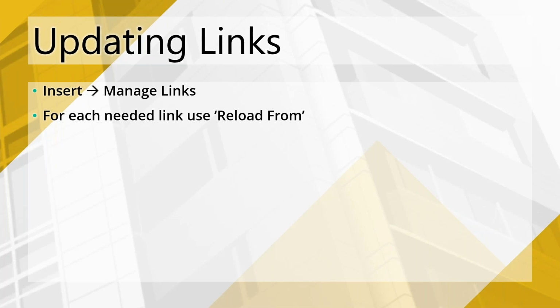Now, this is the note that I want to make sure that you understand. And I've seen people do this and it causes them pain in the future when they do get models. I recommend that you do not remove links that you don't need right now today. Chances are, at some point in the future, you may need those links. And our view templates are already set up to understand how they're supposed to work. But if you remove them, all of the view templates across the entire MEP Productivity Pack forget about those links. And when you relink them in the future, you will have to manually go set all of them up. And that can be frustrating.